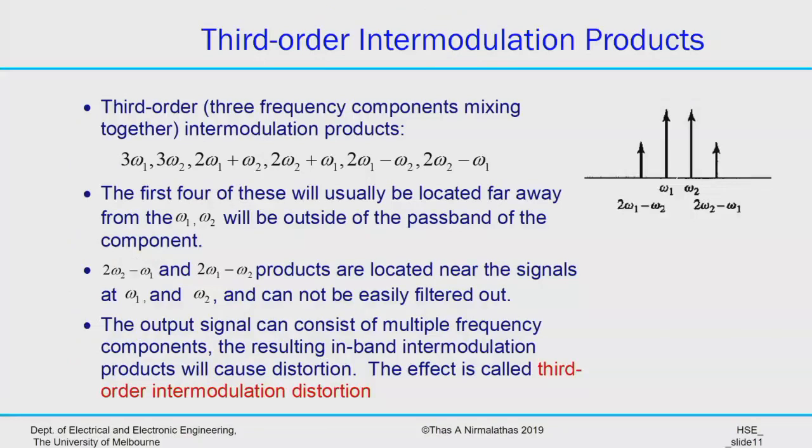Third order intermodulation is one major thing that you normally need to manage, and I already told you about the second harmonics. When the frequency bandwidth doesn't include the second harmonic, it's not an issue; it can be filtered out. But for the third order, we need to know how to design with minimum third order intermodulation, but also how to manage other people's third order intermodulation distortion.